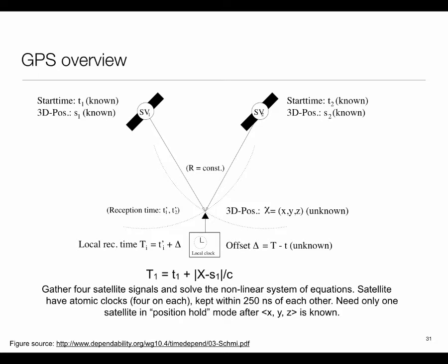So many GPS boards, if you buy the raw versions of them, have a pin that they pulse every second. The idea is that this 1 second is aligned with the UTC 1 second. So you essentially have a ticking signal at the 1 second boundary coming out of all such GPS receivers that have that kind of pin, and they are synchronized ideally to the same degree as the GPS satellites are. Now, having said that, there are of course lots of inaccuracies.